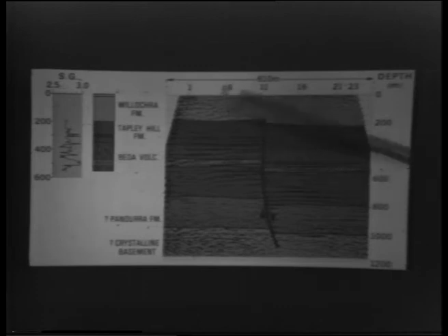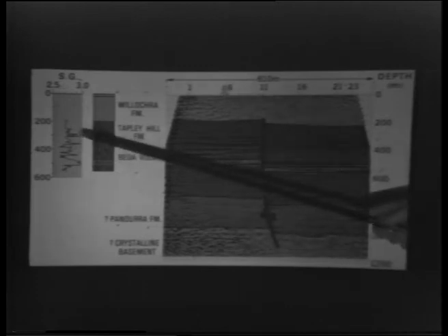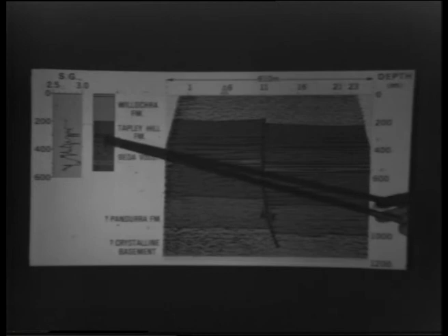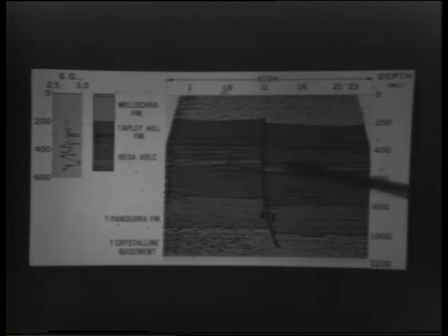The hole is there on the section, and you can see these two little bands in particular correspond to these two reflectors here. The top of the volcanic formation correlates fairly well in here, and this massive trachytic flow in here. There's a change in character, which I've postulated as a different formation here, and another change in character down there. The overall dimensions are 610 meters this way, and a depth of about 1,200 meters down here.